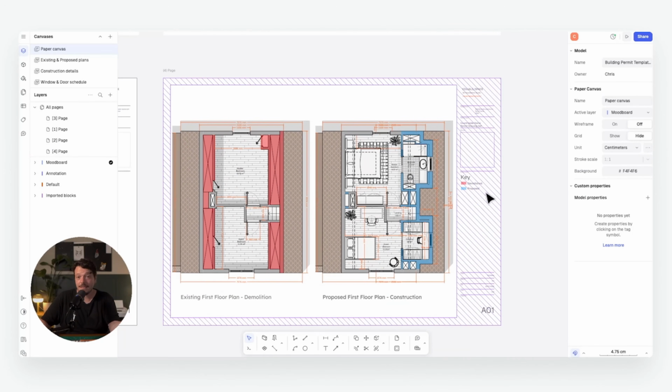And that's your drawing set up. Nice, neat, tidy, very, very clear. Obviously they fit nicely on a page. They're at a good scale, and they communicate clearly what you have and what you're trying to achieve. Obviously moving forward, we can use the existing and proposed floor plans as we see fit. So we can create smaller scale versions of these to be read in conjunction with the sections and the elevations that we're going to be drawing next time.